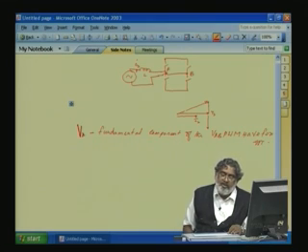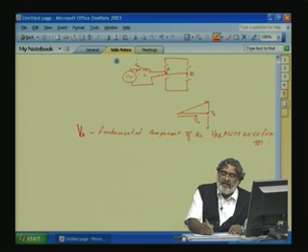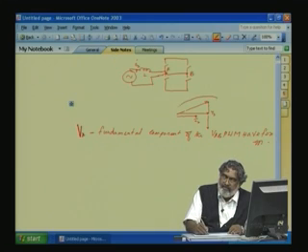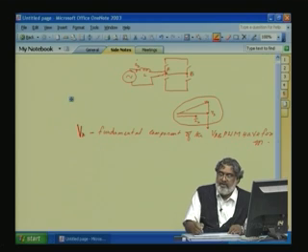Now, assuming the harmonics are highly suppressed, due to the fundamental there is a drop across this inductance. So, from this diagram, what is the relation between the fundamental voltage, the inductive drop, and the VAB waveform?